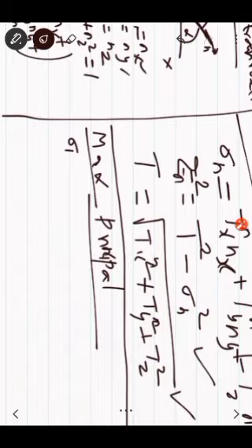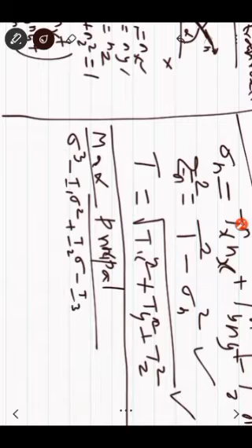If anything is lost, just write the characteristic equation. The characteristic equation is sigma cube minus I1 sigma square plus I2 sigma minus I3 equal to 0. This is the characteristic equation for any three-dimensional stress.